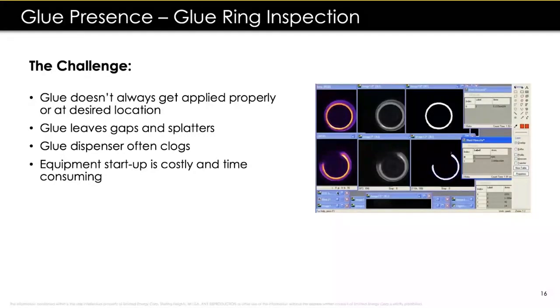So it's a very interesting project. They can get very deep and somewhat complex, but the result of doing this process control is very good. Typical vision systems, especially if you're using adhesive that's, let's say, black adhesive on a black product, that's very challenging for a standard vision system. But we try to apply the same analytics and validation processes with the thermal imaging.